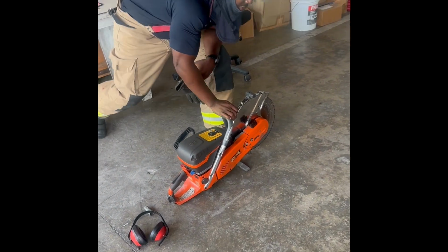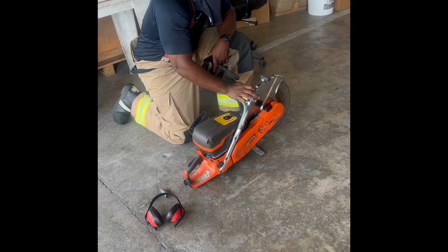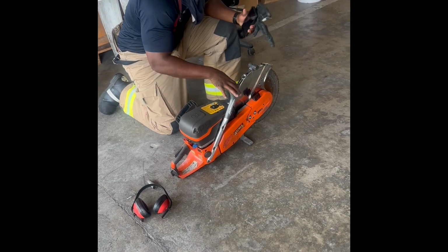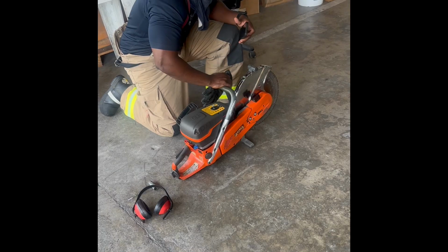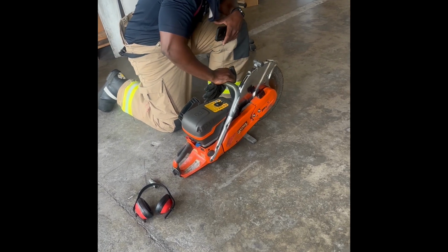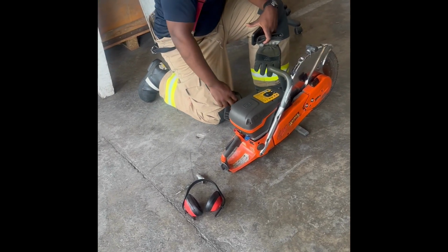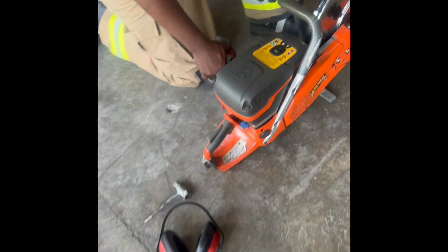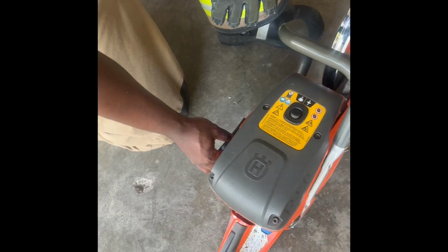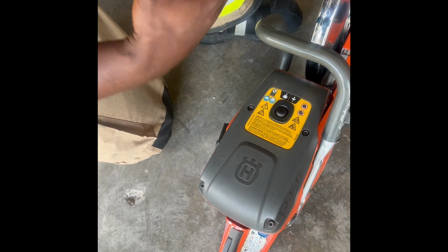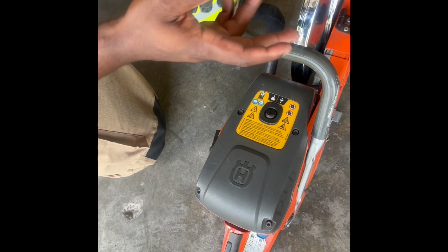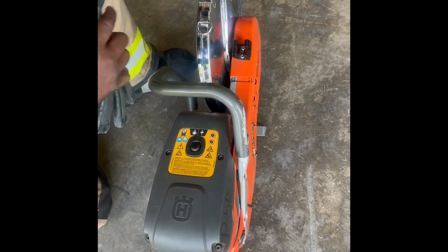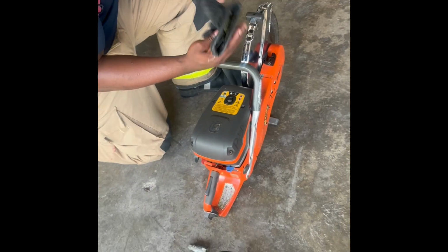So for the weekly, you can check the vibration alternator, make sure it's not broken, not damaged, and properly intact. One of the weekly inspection items is the cord. You want to make sure there are no tears, no wear, nothing damaged on it. Some of the monthly inspection checks can be the air filter, the spark plugs, and things like that. Things like that maintenance would be doing.